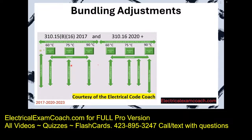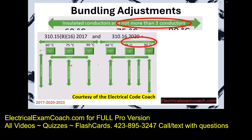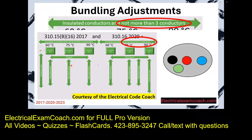It says, hey, these are the ampacities of these conductors if, and the first if that we're going to look at is if there are not more than 3 current carrying conductors inside of a cable, pipe, or even buried in the earth together. Let's imagine that we have a piece of conduit here and we pulled in a black, red, blue, and an equipment grounding conductor. What this table is saying is that those ampacity values listed down below in this table are true as long as you have not more than 3 current carrying conductors in a cable, pipe, or raceway. If you do have more than that, then we have to do what's called a bundling adjustment.